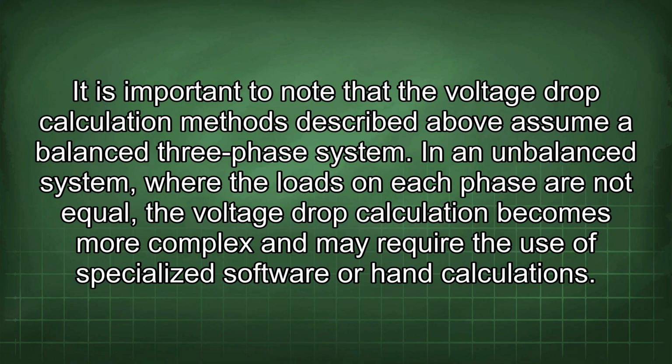It is important to note that the voltage drop calculation methods described above assume a balanced three-phase system. In an unbalanced system, where the loads on each phase are not equal, the voltage drop calculation becomes more complex and may require the use of specialized software or hand calculations.